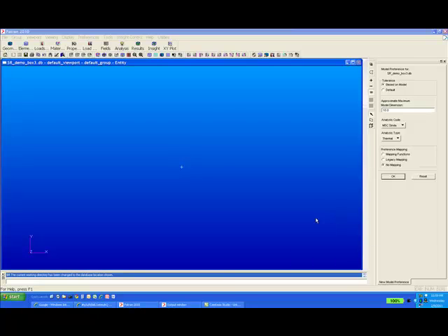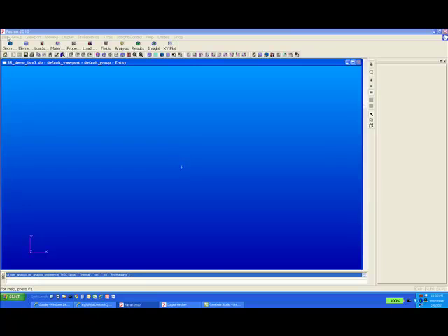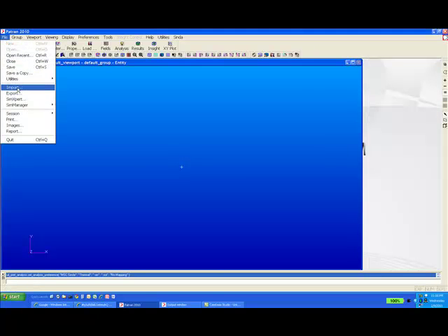In this demo, we're going to show how to use MSC Sinda and Patran along with SindaRAD to do some advanced thermal problems involving radiation. We're going to go start to finish, and I'm first picking the MSC Sinda preference, and I'm going to load in a piece of CAD geometry.